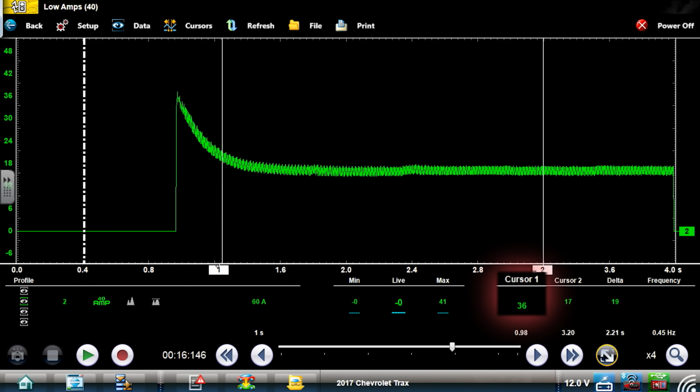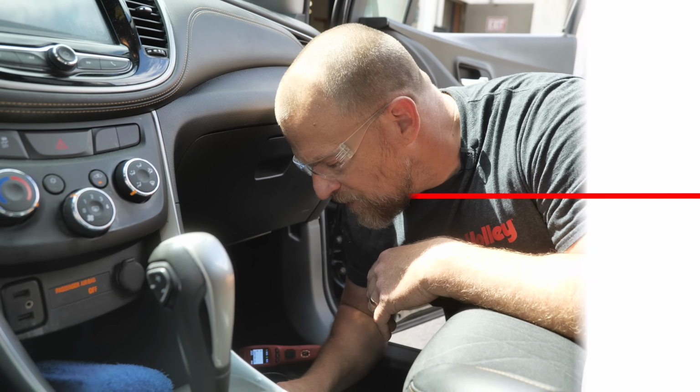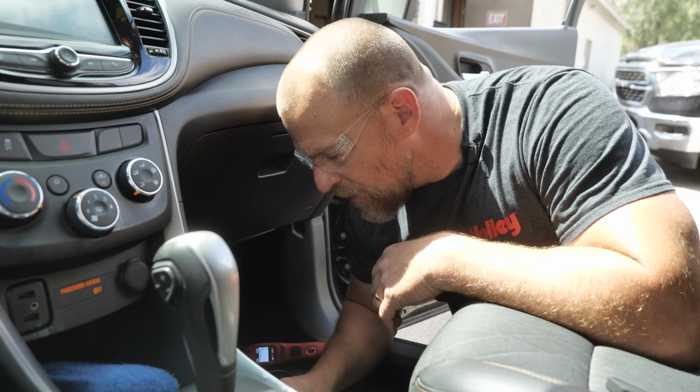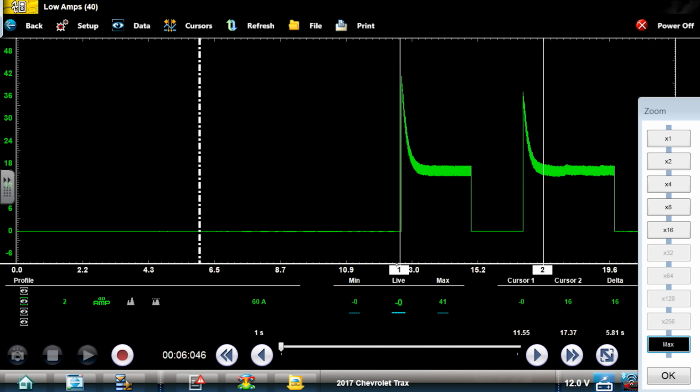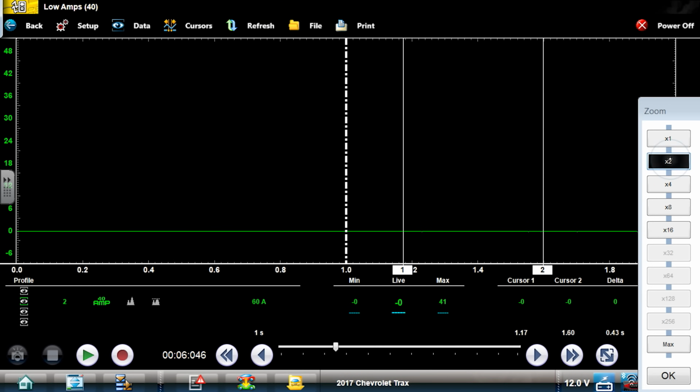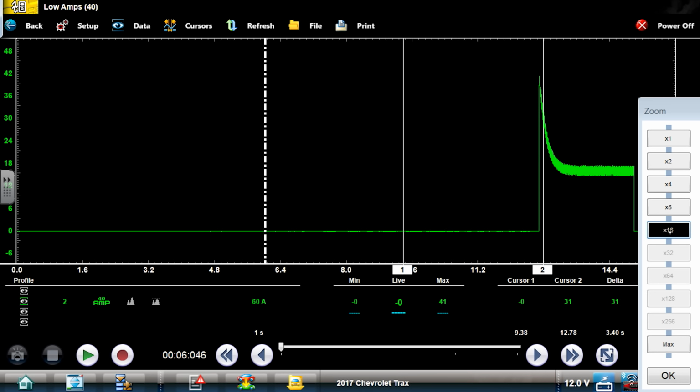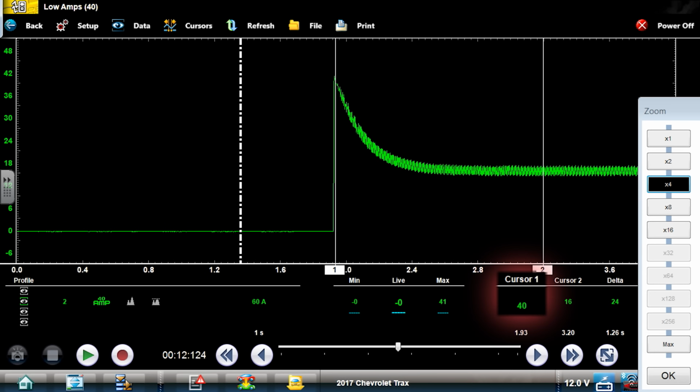And that's typical of an electric motor. Then down in here, an average amperage of about 16 amps of current, and that's going to be blower on high. I have no problem with that. So now I need to talk to Pete. Final thoughts, but I just wanted to get one more measurement here for you guys. It looks like this first one had even higher amperage, but it still doesn't bother me. This is good. Yeah, it's 40 amps on that peak, but it's like 16 amps after.